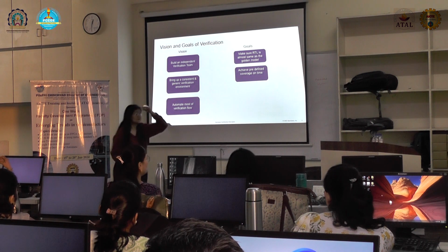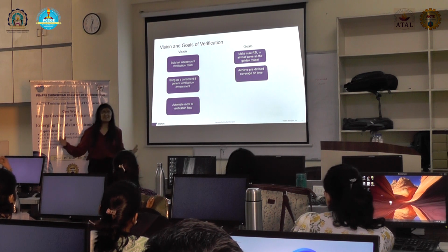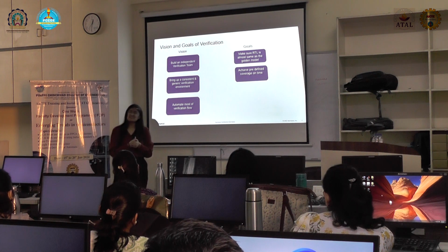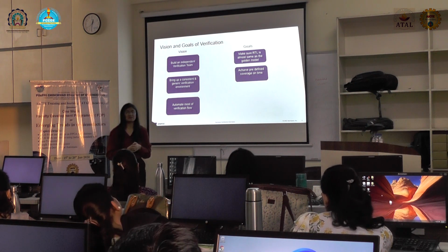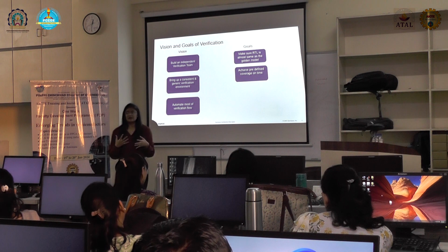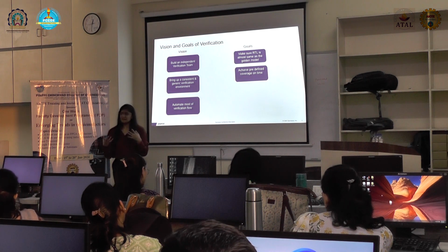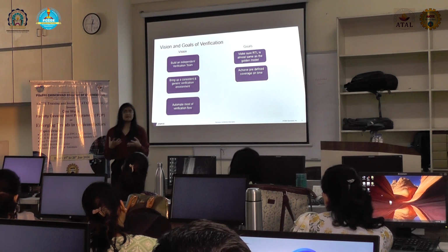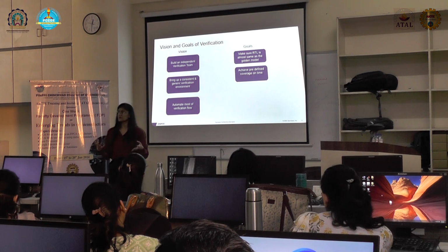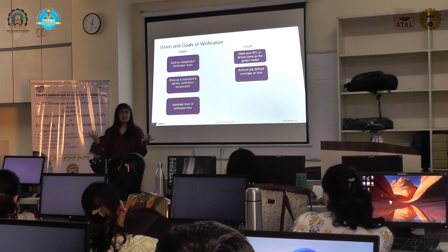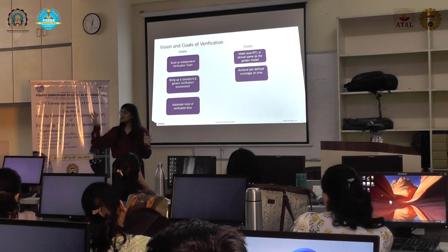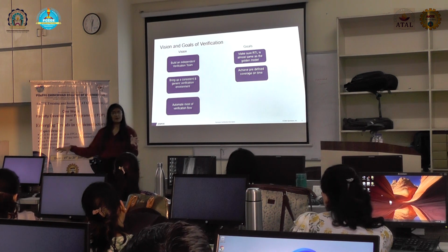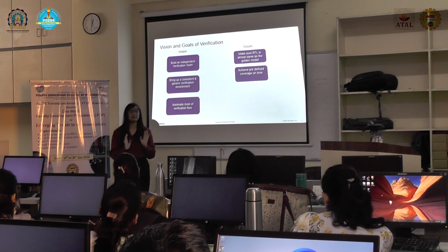Okay, so the next step is coverage. As I'm talking about coverage a lot, a verification engineer's main focus is on coverage. What is coverage? When we are enabling randomization, there should be a matrix that collects all the information. We can randomize anything, but there should be a matrix that specifies that, according to my product or my requirement, I have collected what I need.